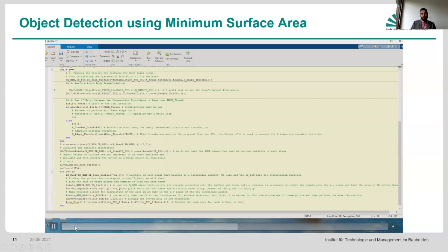This is the area we're going to get for our basic solution that we'll compare with the original area. So we're finding the point cloud coverage area for each surface in the BIM. That means this is the surface covered by the point clouds that have been recognized as being projected onto that particular surface by means of the dist threshold and the RMSE threshold, right?